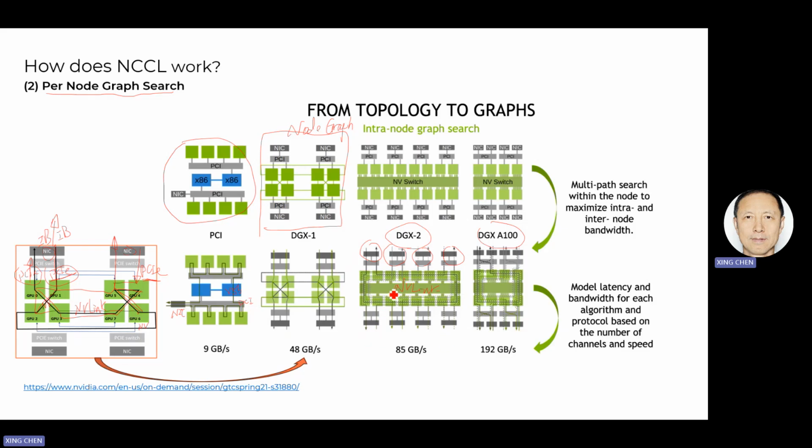For inter-node communications, the total bandwidth the GPUs of this node have to communicate with GPUs connected to other nodes is 8 times the PCIe link bandwidth, because you have 8 PCIe adapters.